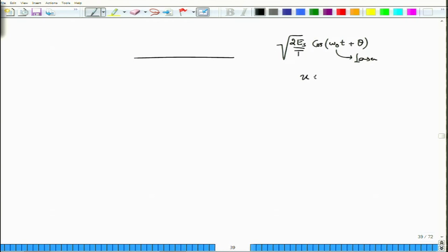Now, I have my signal u of t, and as we have seen earlier, one of the natural ways of converting an electrical signal into an optical signal is to modulate the phase of the optical carrier, right. So, I can modify the phase of the optical carrier, and in order to do that I will be using a phase modulator. What if you choose u of t such that it will either produce 0 volt or V pi volt? When you send u of t with 0 volt, the output and input electric fields are in phase with respect to each other. So, you can think of this as 0 phase being transmitted.